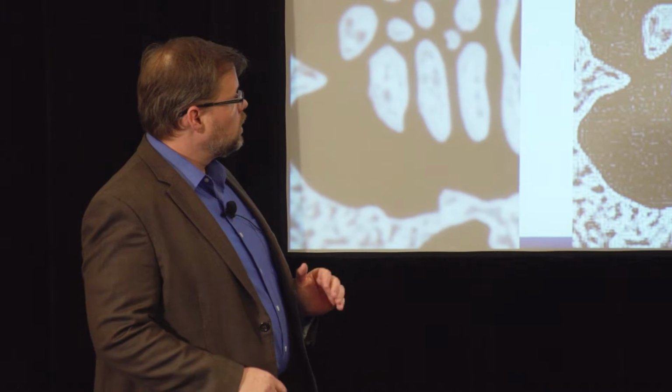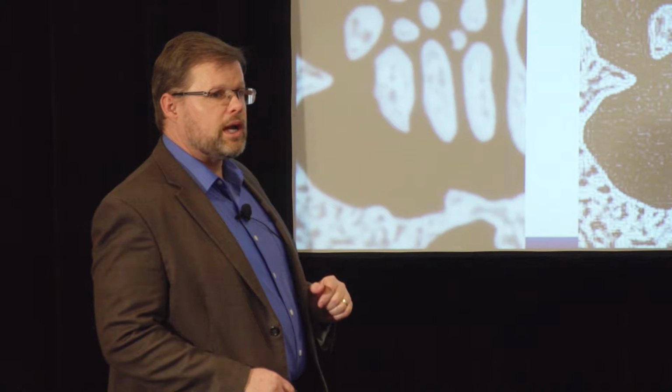Then you're able to do about 4 times as many images a second. You go to 98 images a second. And that includes the round trip of pushing the image down to the FPGA and extracting it. And if you have to do the convolution step 10 times, because you really need to crisp that image up, which is also common, the host system can only do 1.5 frames per second.